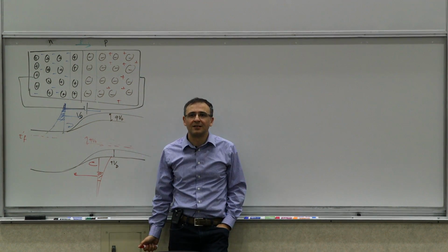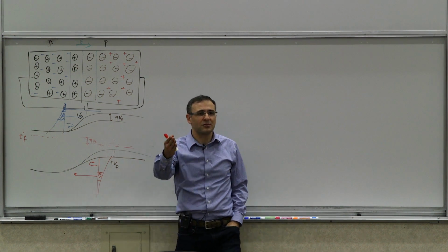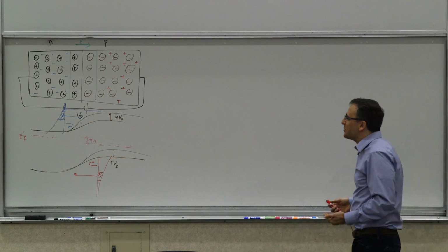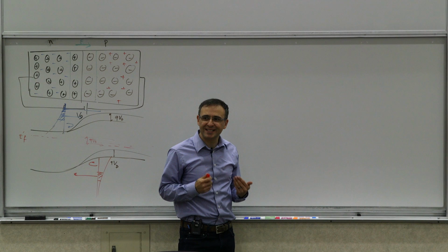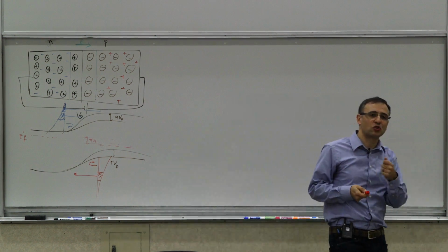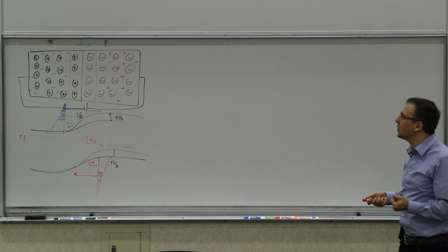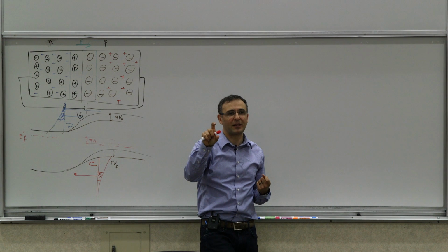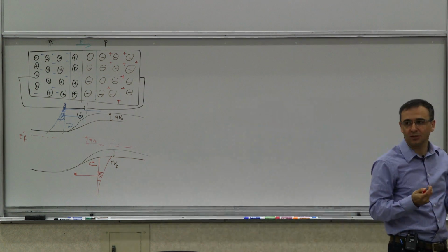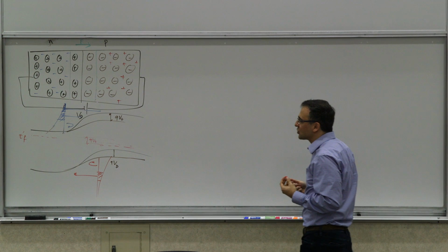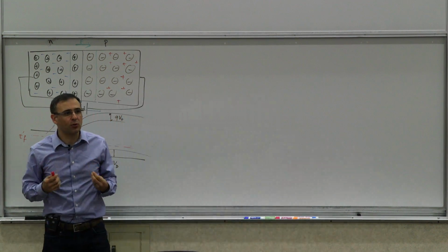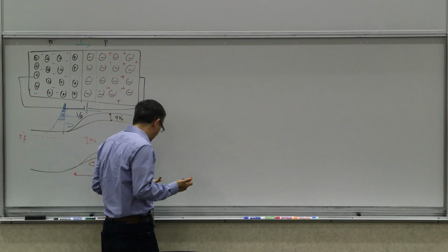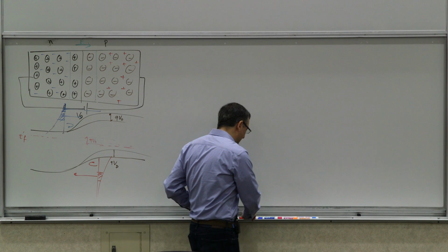You can't control it with some other input. Right, exactly. So the response was you cannot control it with some other input, which basically means that you really need a third terminal. You need to separate the controlling terminal from the controlled. Because here the controlling and the controlled are one. You have these two terminals which basically make one port. You need to have at least one more terminal to control what's going on. So this process of making a bipolar junction transistor from a pn-junction diode is based on that. I mean, fundamentally, it's as simple as that.